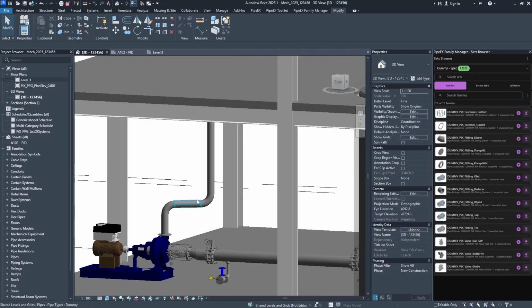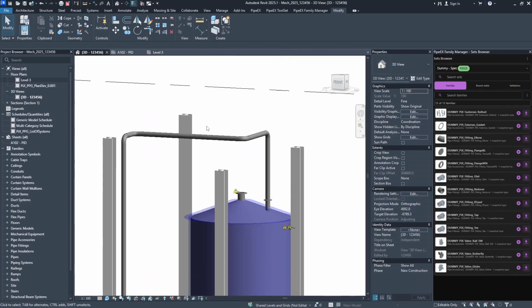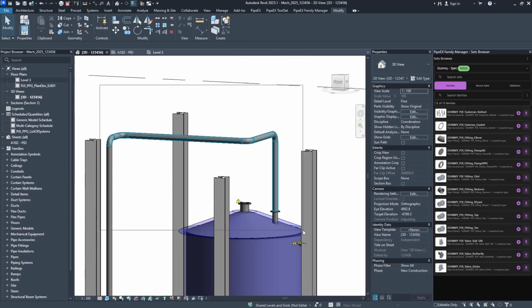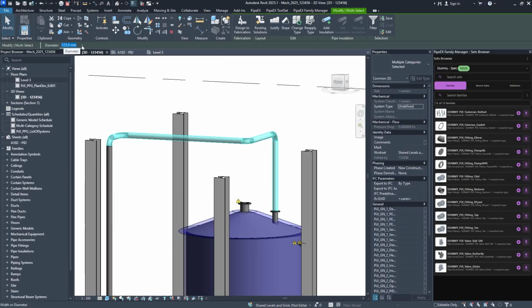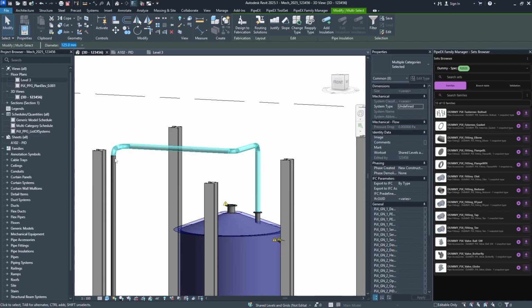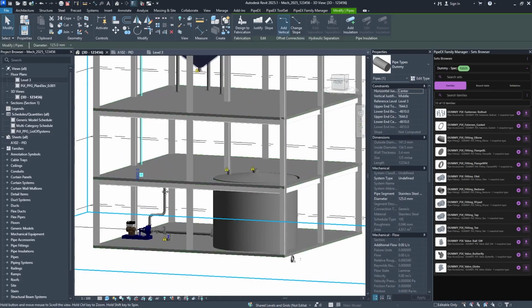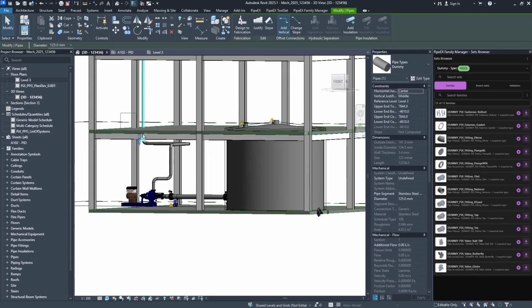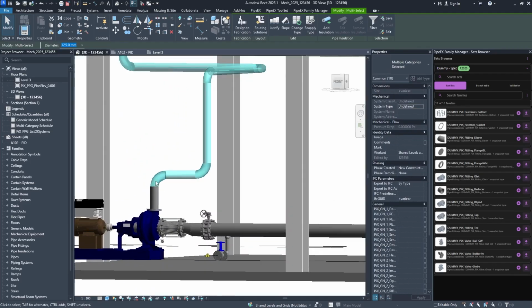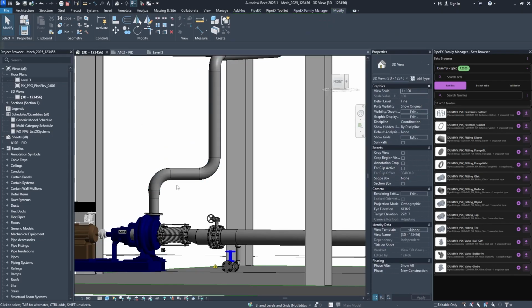And for sure we also need to change the diameter, because this is the thing that I forgot to do. How can you change the diameter of the pipe of the system you already drew? Actually here it's quite simple. You can select the section of the pipe you would like to modify, and you can just simply change it to 150 in my case. Like that. And then we can just continue till this elbow I have over here. I'm also going to change it to 150.